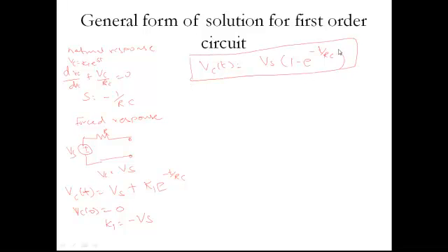Okay. So here RC is the time constant. Tau is equal to RC. If you are taking an inductive network, please understand tau is equal to L divided by R. For a capacitive network, tau is equal to RC, whereas the form of the equation, everything is one and the same. Okay. So this is the introduction of how to write the differential equation and how to solve the differential equation.